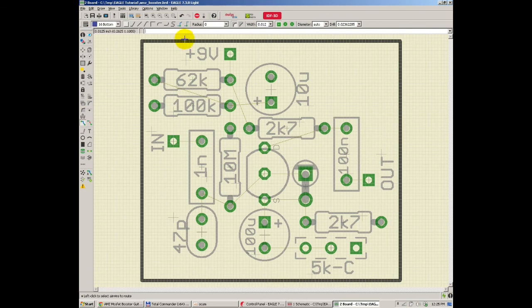That will be wire bend style one, and this will ensure that your angles will stay at 45 degrees. Also, you don't want the corners to be rounded, and I'm choosing straight miter wire.